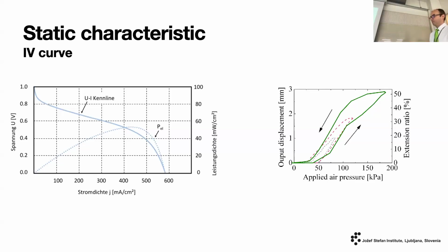So first things first, we have to find whether our system is linear. It's not. Mother Nature doesn't provide linear systems, or only very, very rarely. There is this joke that there are two types of differential equations, solvable and useful. Everything that is useful is most probably not solvable. So what we do is we do an IV curve and we try to find a set point where we can say that our system is sufficiently linear, or as close to linear as possible.